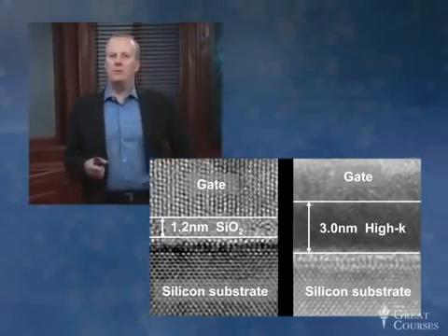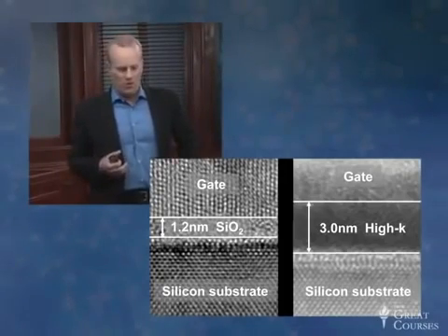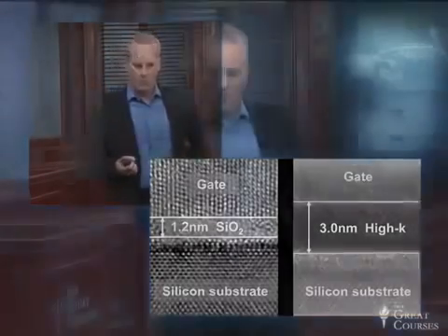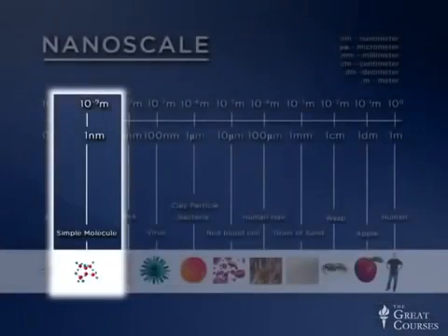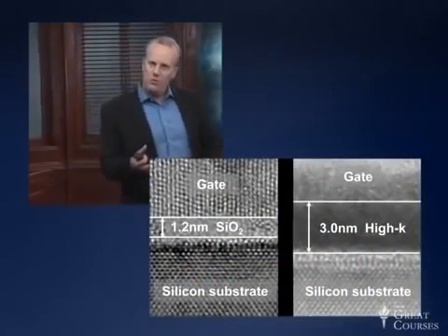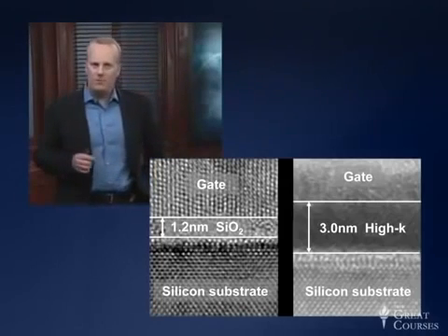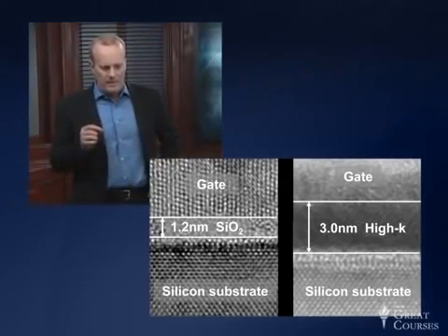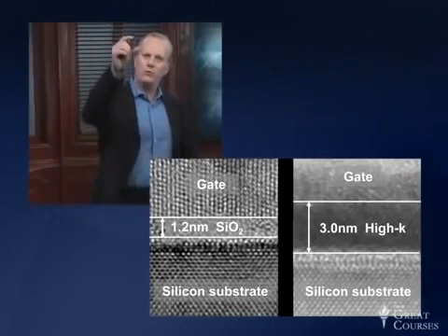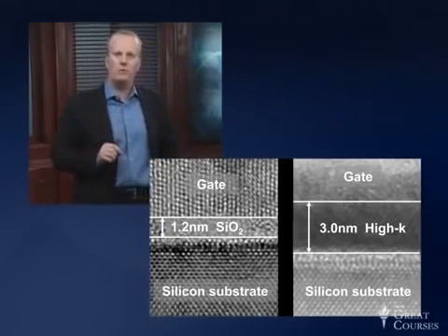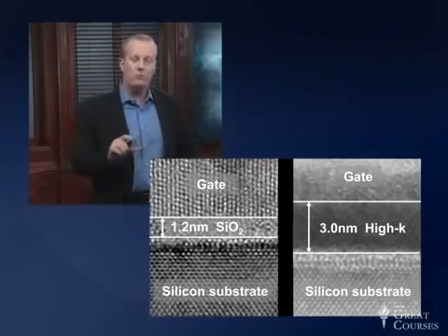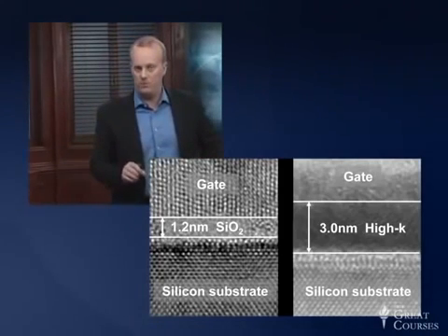In fact, this is another illustration of our concept from earlier lectures on how small you can confine waves. We're able, using electrons, to see things as small as electrons, to see things on the scale of about a nanometer. There's no way you could take pictures like this using visible wavelength photons, which are so much larger. Now, this is showing a gate oxide that's a couple of nanometers thick. And it needs to get so thin so that we can control, through the gate, the formation of the channel beneath. We can't have our gate electrode be too remote from our channel in order to effectively control it.